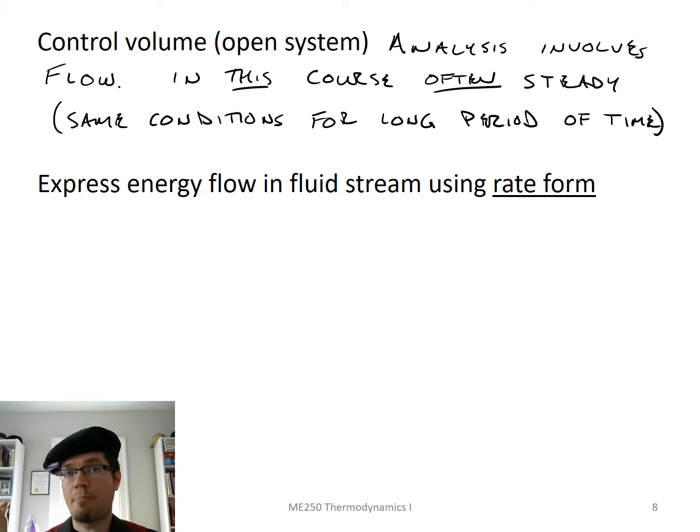If you turn on your tap and then let go of it, it's running at a steady flow rate. If you take an empty cup of water and put it under that tap, the flow into the system, being your cup, is steady. The system, being what's in the cup, isn't steady. So you can have a non-steady state system, a transient system, with a steady flow into it. And it is as simple as saying, what's the flow of water into my cup? What's the rate of change of liquid in my cup?